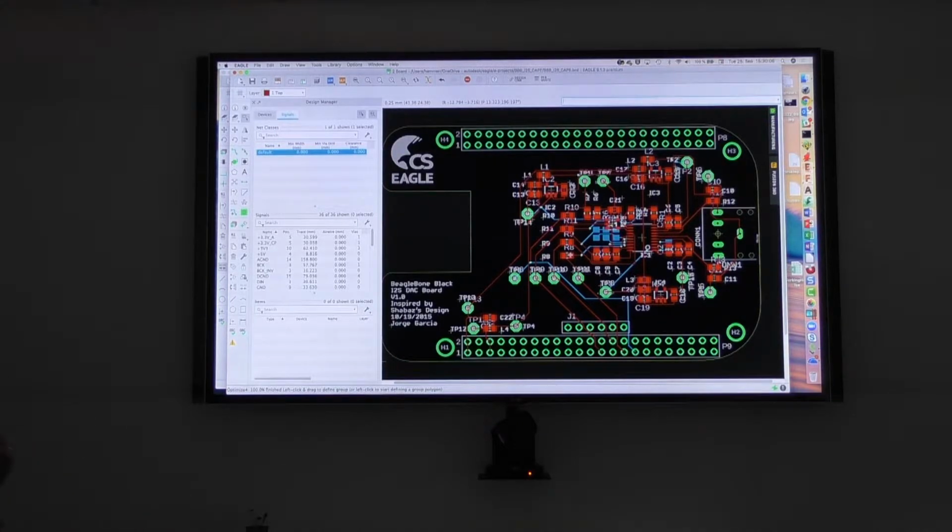If I would have done a bit more investment in design rules, and what I did not yet mention are net classes. You see the router takes the 150 micrometers from the design rules, and all the traces have the same size. I could define net classes and say my ground net has to have this width, these nets have to have that width, so I have different width values for this. Then the autorouter would follow the net class settings, and then it's a bit more structured, I would say.